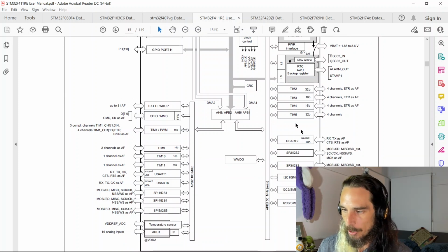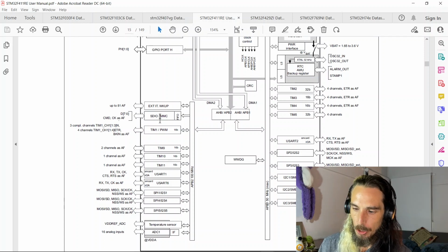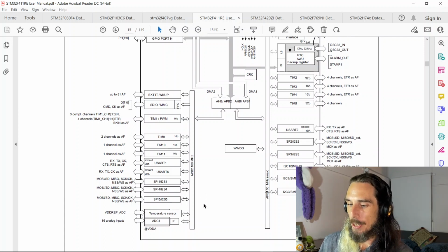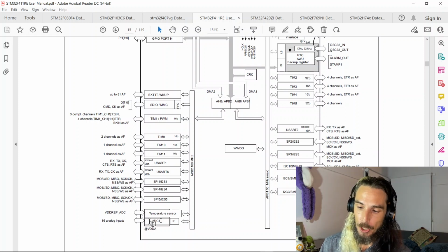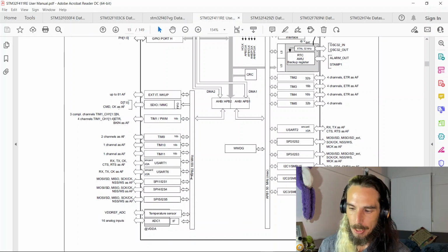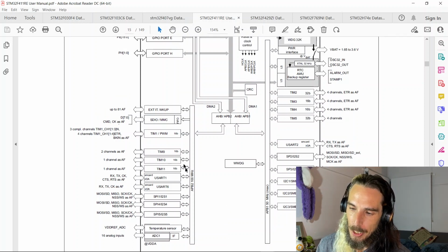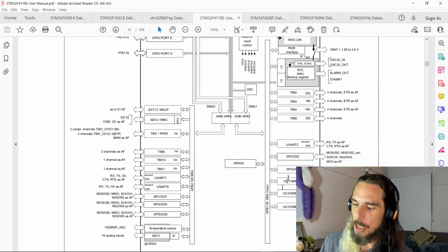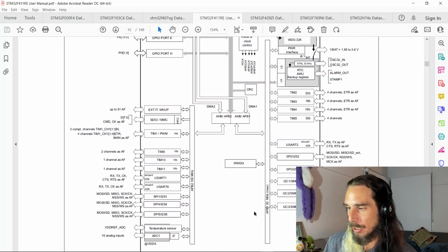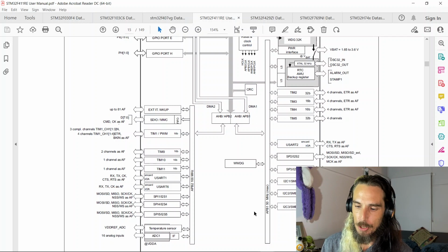And connected to either of those, we've got a selection of different peripherals. There are commonalities there as well, so you typically find the analog to digital converters are going to be connected to peripheral bus 2, and you'll normally find those down the bottom left of the diagrams. It's handy to be aware of which bus a particular peripheral is connected to, because, depending on your clock selections for that peripheral, that can determine what clock rate it is actually going to be operating at.